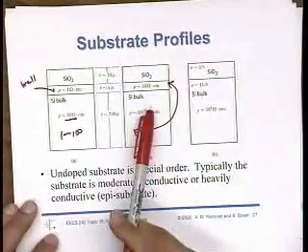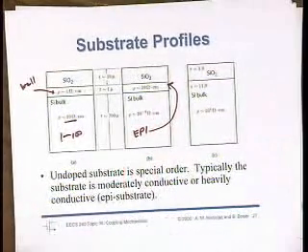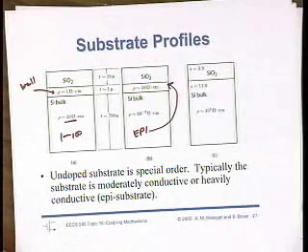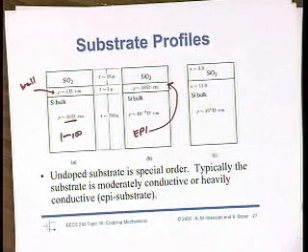So this is very good for preventing latch up. Unfortunately, we'll see it's very bad for substrate coupling. It's also very bad for RF circuits because eddy currents can flow here and reduce the quality factor of our components.